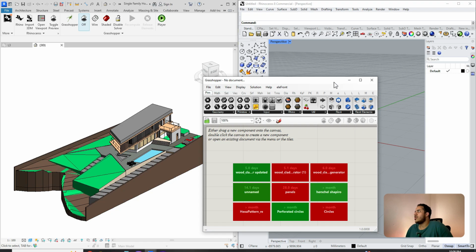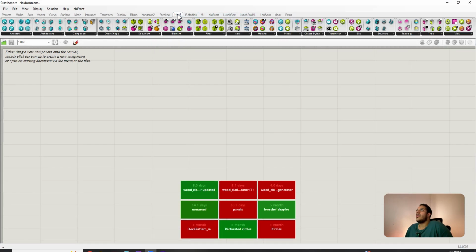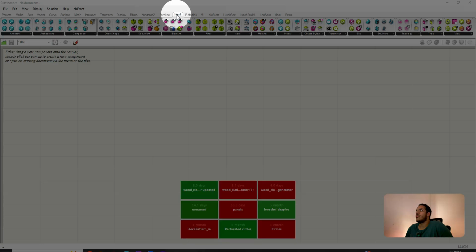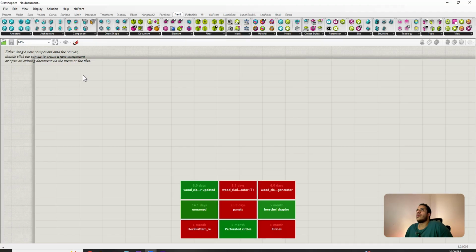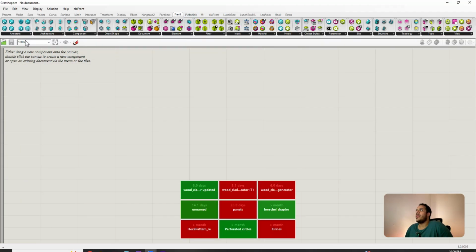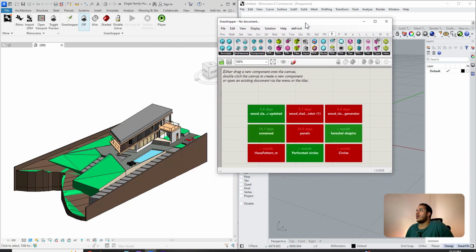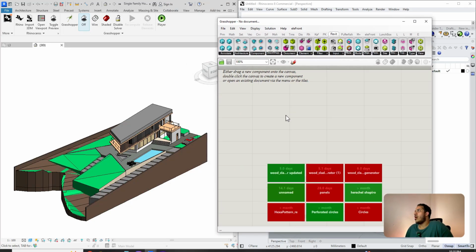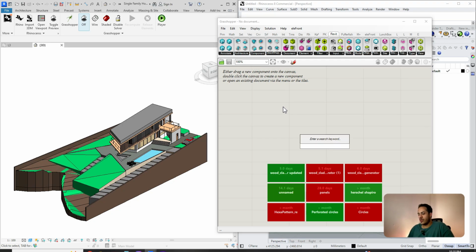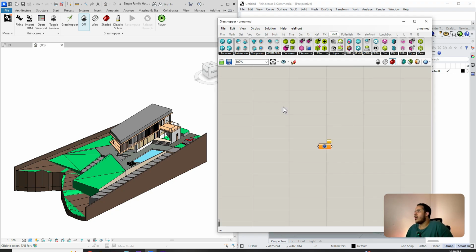Okay, so here in this bar, you will find hundreds of components that you can use to go deeper and control anything in Revit inside Rhino. But for now, I want to use only one component that is called graphical element, which you will find in the parameters for Revit.